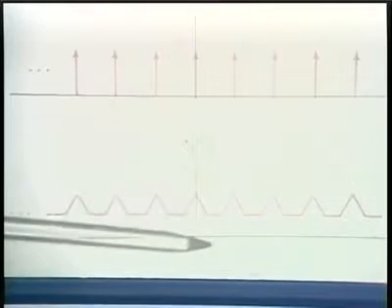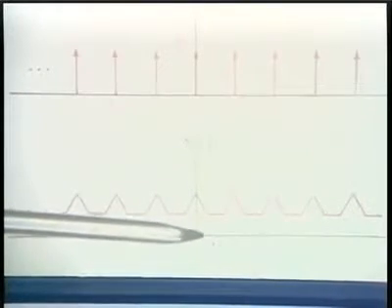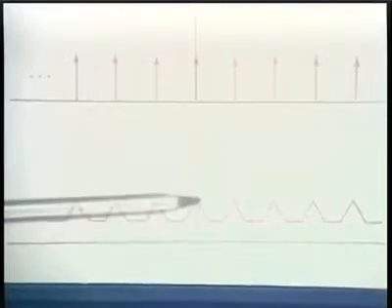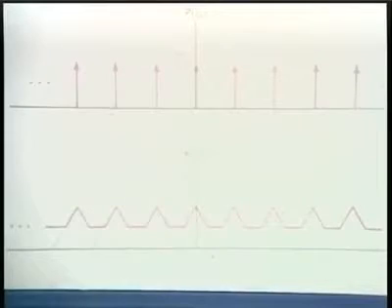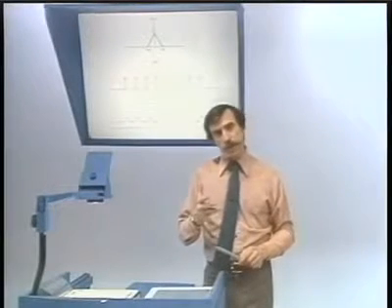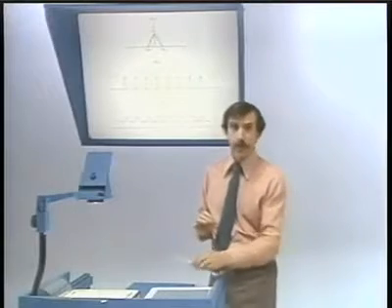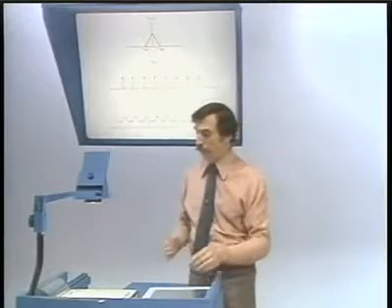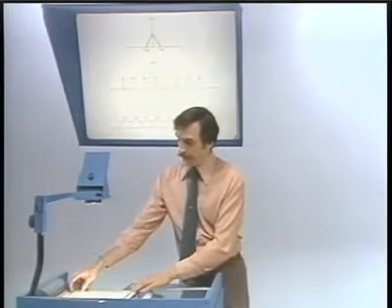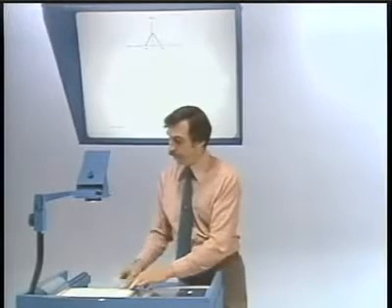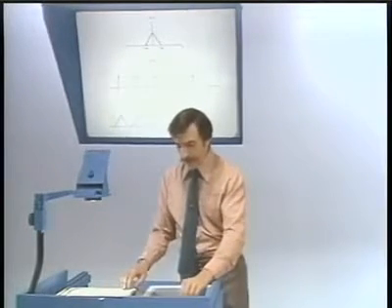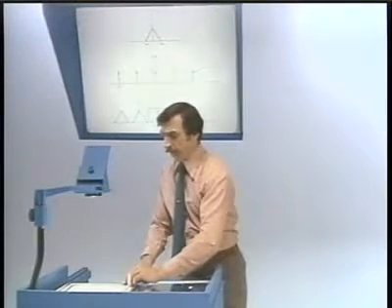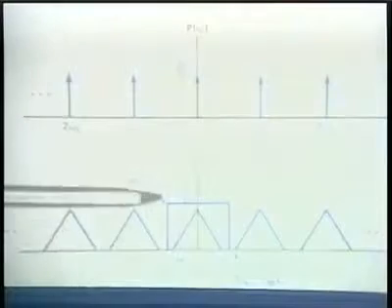And that would be true also in the more general case of pulse amplitude modulation with pulses of non-zero width. This effect, by the way, is one that we'll be exploring in considerably more detail in the next lecture, and it's a phenomenon or distortion referred to as aliasing, which is an important and interesting topic. But going back to the case in which we've chosen the frequency of the impulse train high enough, then we would recover the original signal by processing it through a low-pass filter.